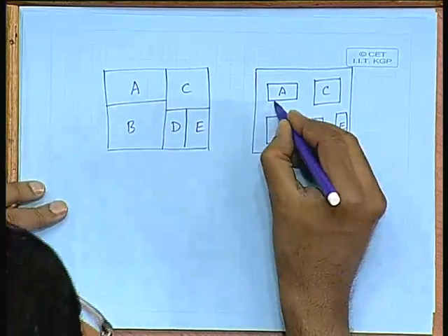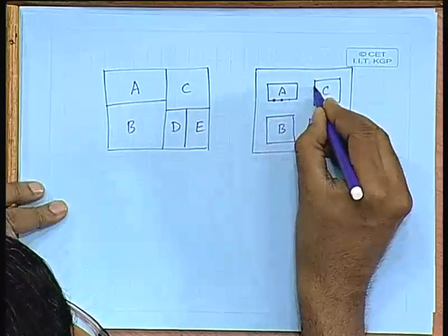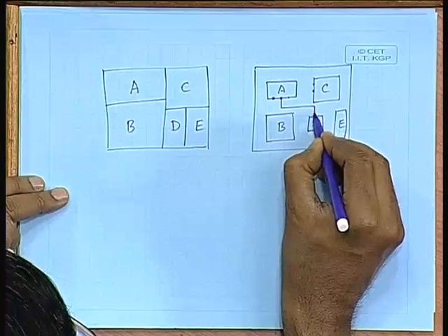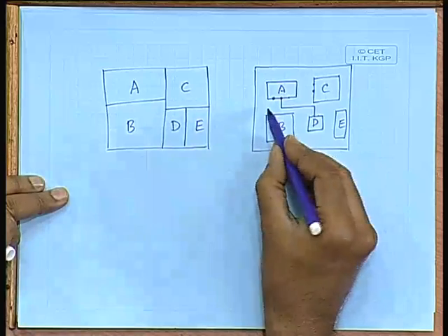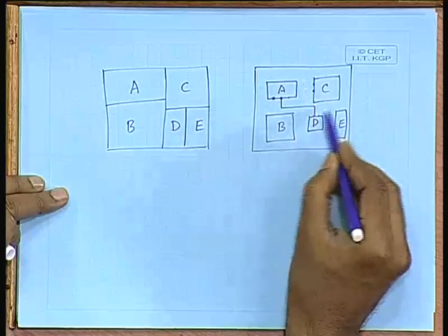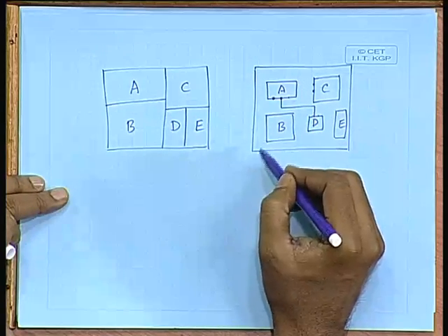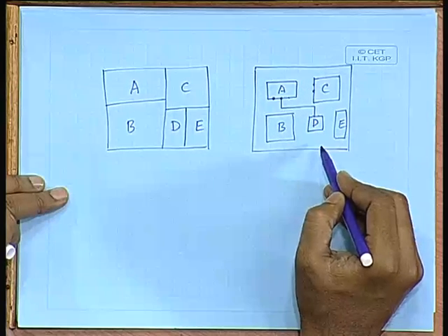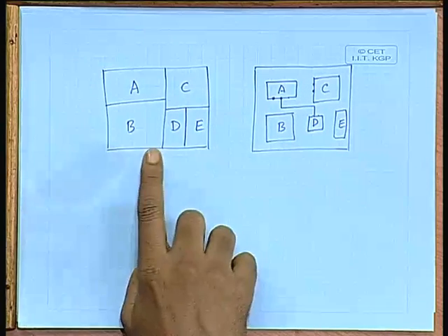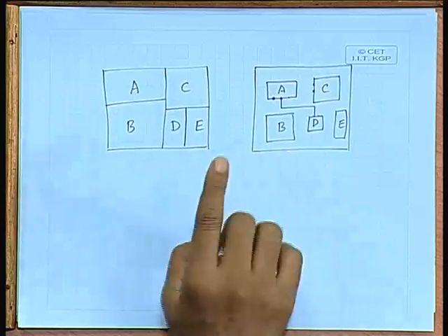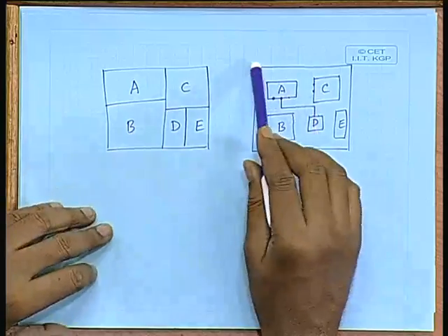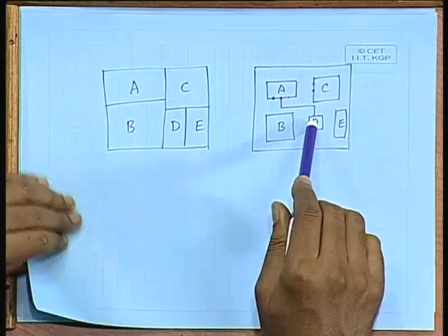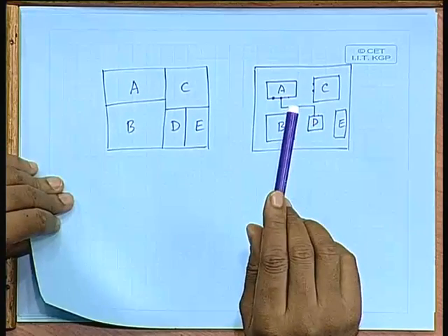Now, in a placement the exact pins have been defined, the netlist has been defined, you also know which pin you have to connect to which other pin of the other block, and the routing or the interconnection areas are also defined, which are the places available for interconnection. So, this is the difference between placement and routing. Now, here what we say is that even after placement is complete, still there is some scope for pin assignment, we will see how.